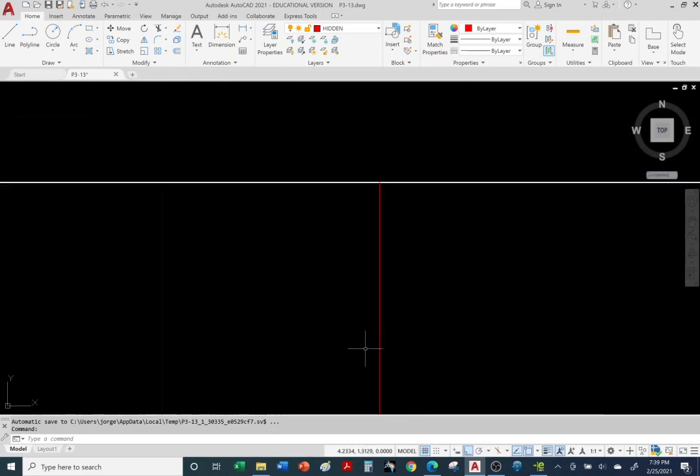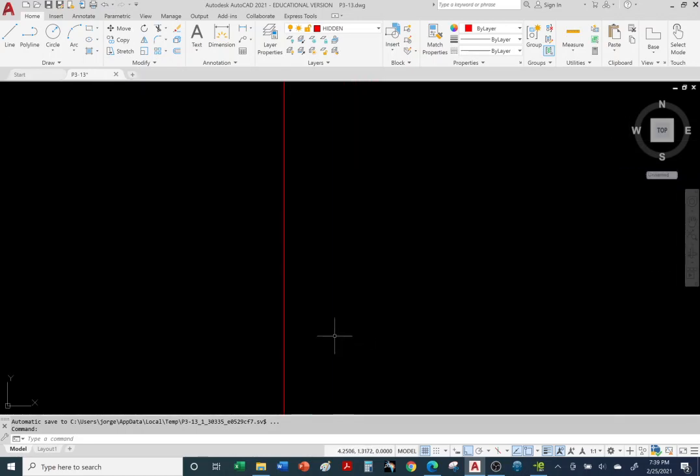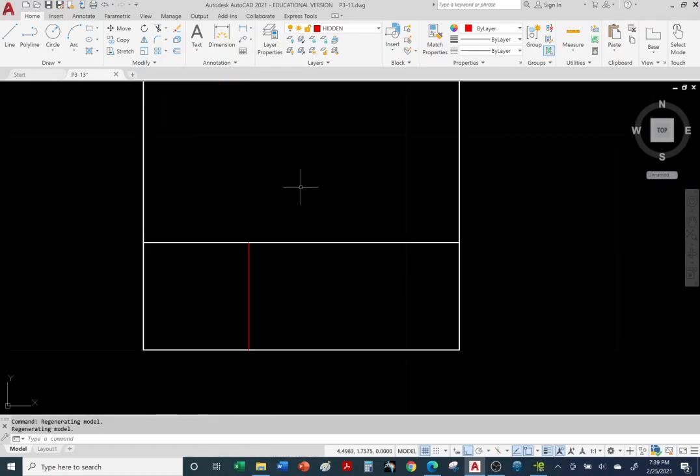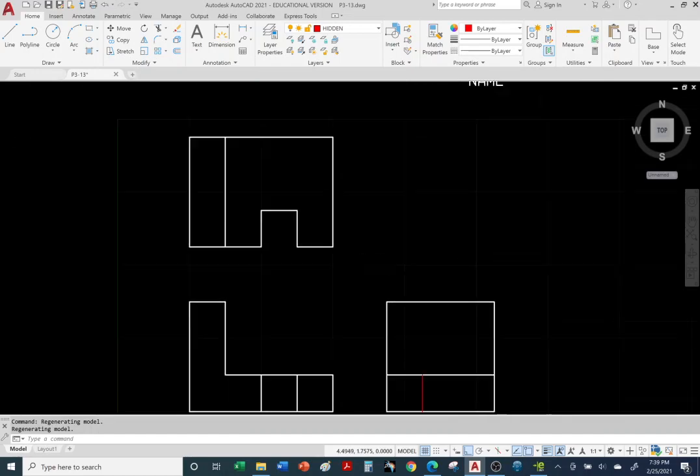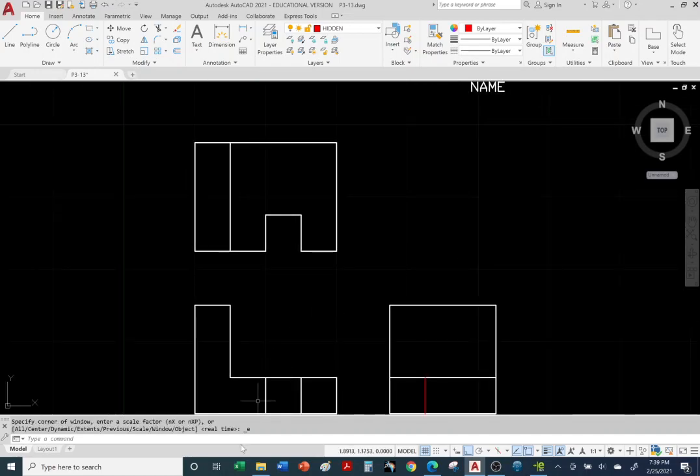And it got worse. If I really zoom in, I'm zooming in, I'm rolling the wheel, and I made it worse. Okay, so let me, oh, there it is. So I actually made it worse. So let me double click on the wheel to zoom fit. Let me type in LTS again. LTS. Not as easy as 1, 2, 3. Hit enter. So 0.01 didn't work. Let me try 1. Go in the opposite direction. 1. And don't blink.